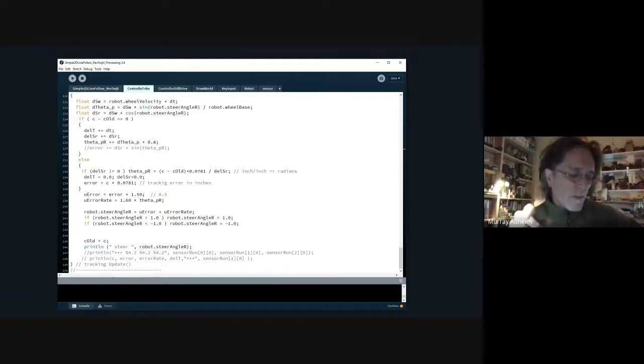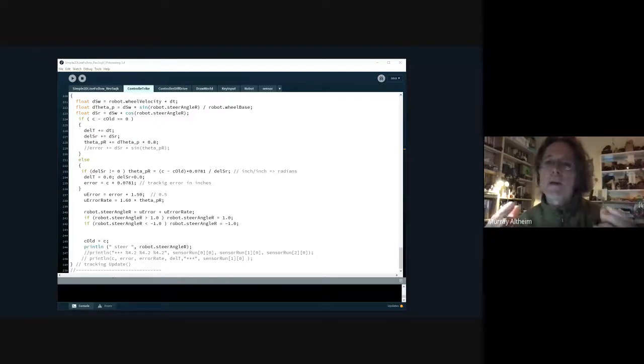I guess the thing I'm thinking is that I wouldn't try to emulate the hardware of your robot. You can buy the Zumo robots and a few other robots, they have a little array of, I think, 5 sensors that you can mount under your robot. My robot's entirely physically different than yours. But if I was to mount 5 or 7 sensors underneath, I'd effectively have a state array, and then I could start sampling off that and try to do what you've done using a very different robot platform. That's what I'm thinking: how would you abstract the cleverness of this approach to a different robot?